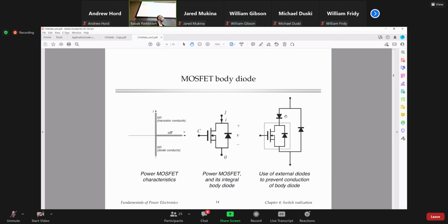So in other words, in my symbol, all of them are the same. All of them are diodes. One is a body diode, not a discrete component. This is a discrete component, but same physics, right? Different characteristics, but same operating principle. Of course, you can pick a bad diode, you can put in a high voltage PIN diode.